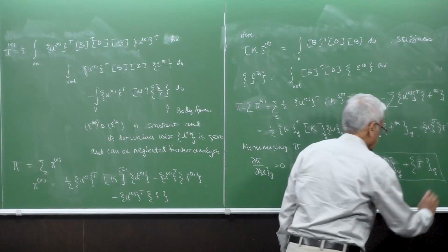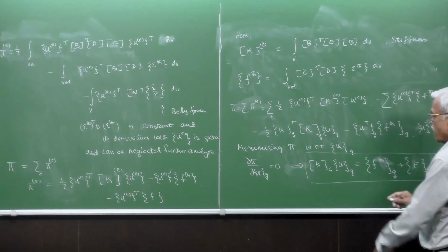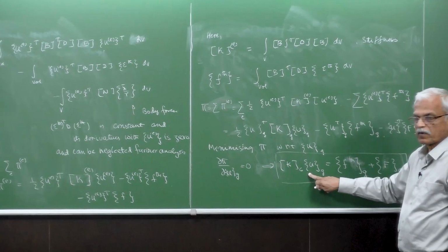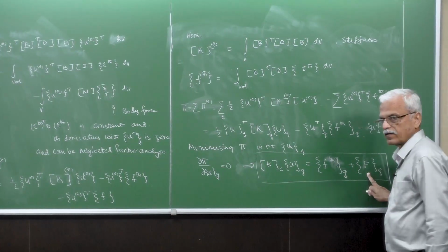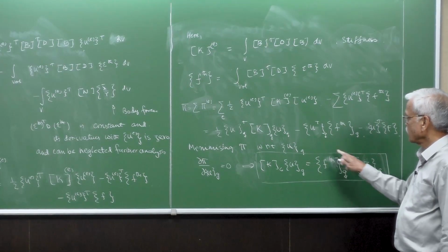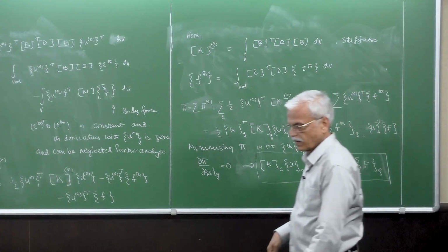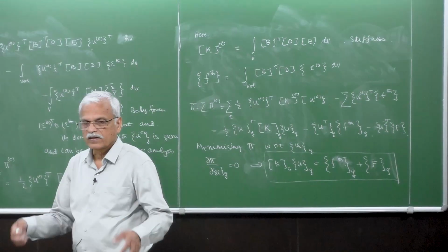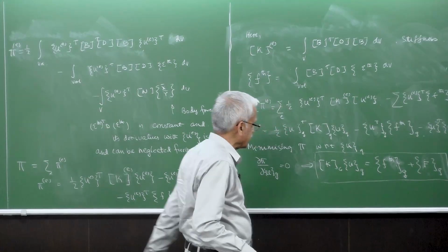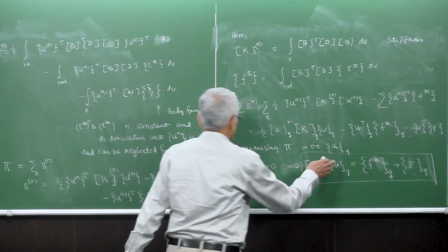As you see carefully, this is nothing but our usual stiffness multiplied by the global displacement vector, and then this is the mechanical load which is applied, and together with this, to take care of the thermal effect, we have a thermal force vector here. So that's F thermal. That is the new term which has come. So you add it into this one, and then solve it as per your boundary conditions.